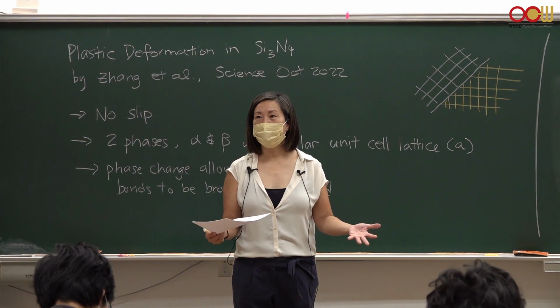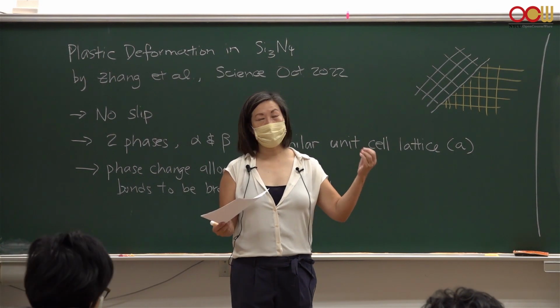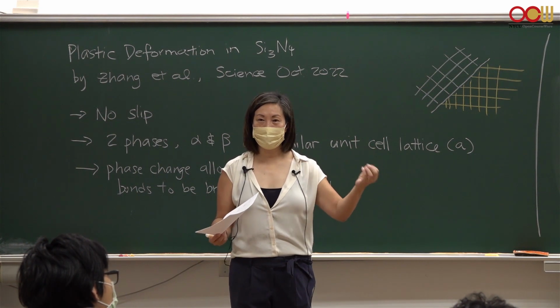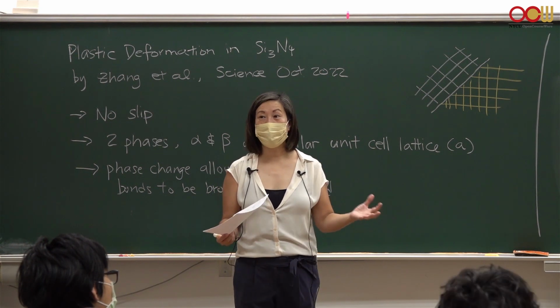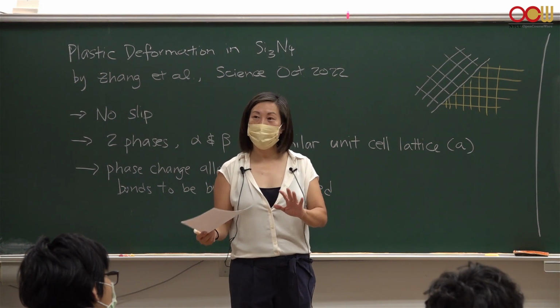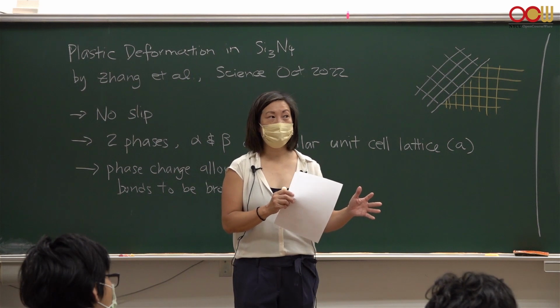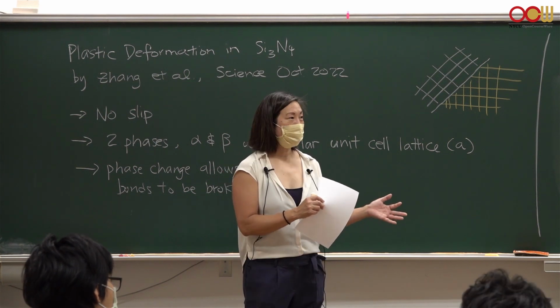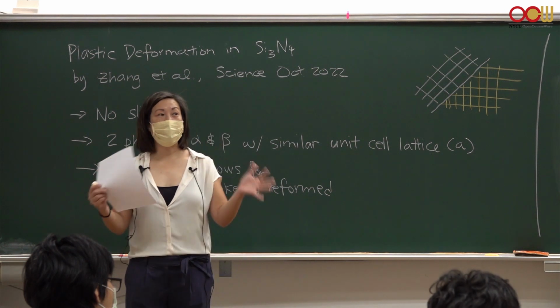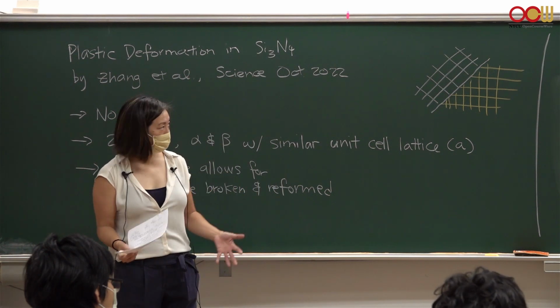It's all the same salt water. But if you exceed the solubility limit and some of the salt becomes crystalline and comes out of the solution, now you have 2 phases. You have the liquid salt water phase, and you have the solid phase that is just salt, NaCl. So you can have 2 phases. When we start talking about solid solutions, you can have many, many phases. Okay, and we'll talk about that in a little bit.